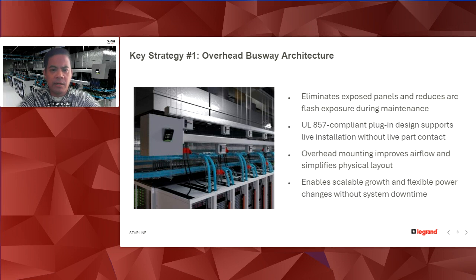I'll also mention we have done voluntary testing with arc flash, where we intentionally set off an arc within the system to see how it behaved. Safe to say there was nothing catastrophic that happened with that test. It was an IEC test that we did. I forget the exact number offhand, but we did pass the criteria, which gives our customers more confidence that the busway system itself is a very, very safe design.